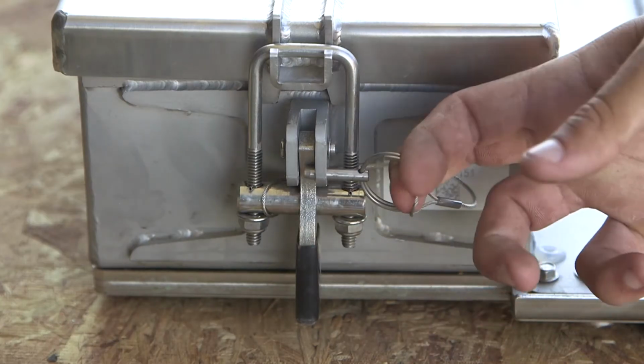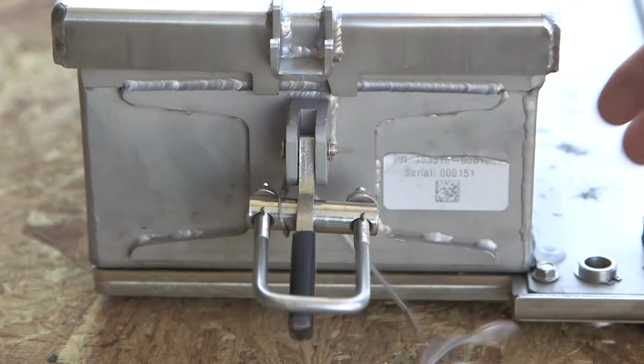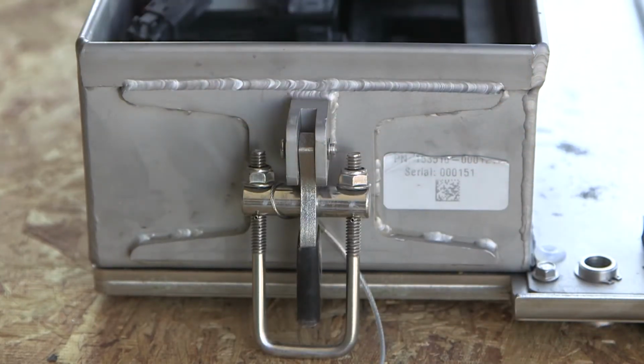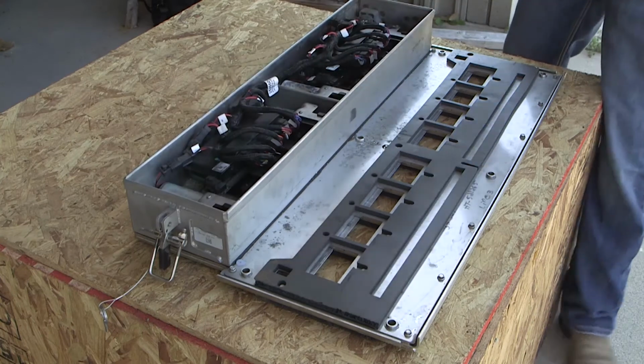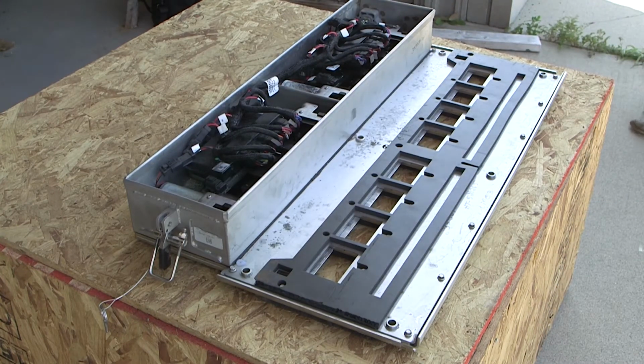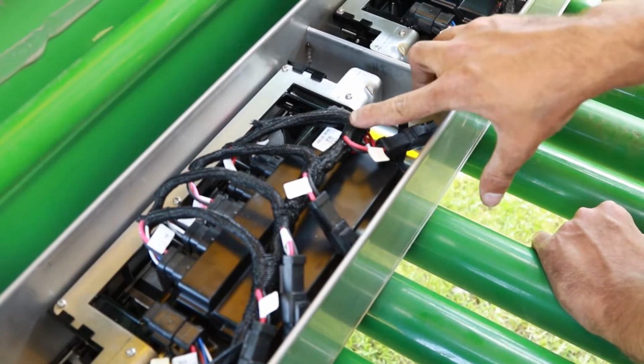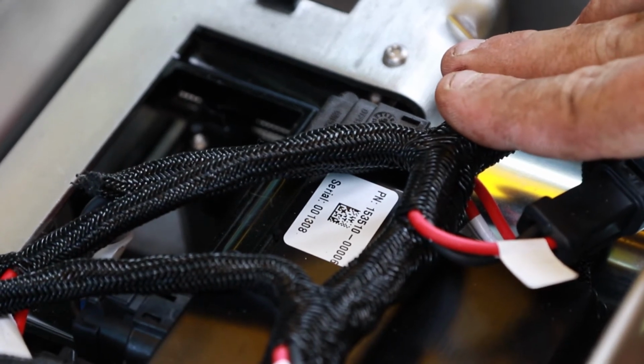A. Remove the cover from the Engage Zone control unit and find the serial numbers on the 2 motor controllers inside each bin unit. Gates 1 through 4 correspond with the serial number on the leftmost motor controller, and gates 5 through 8 correspond with the rightmost motor controller.